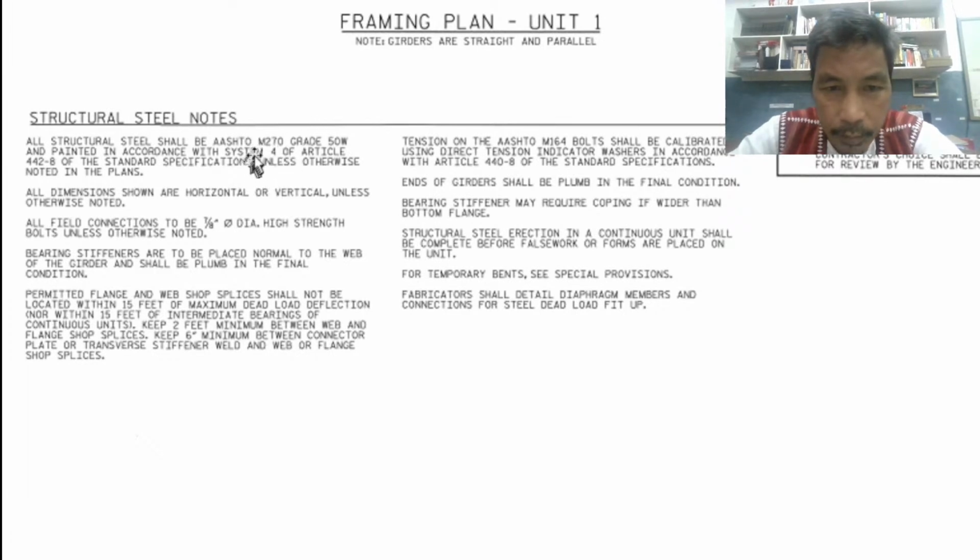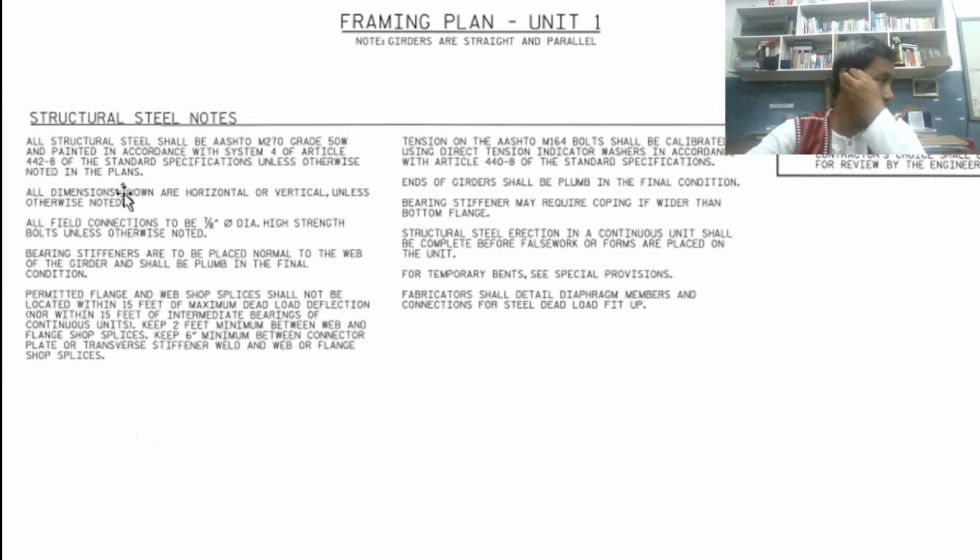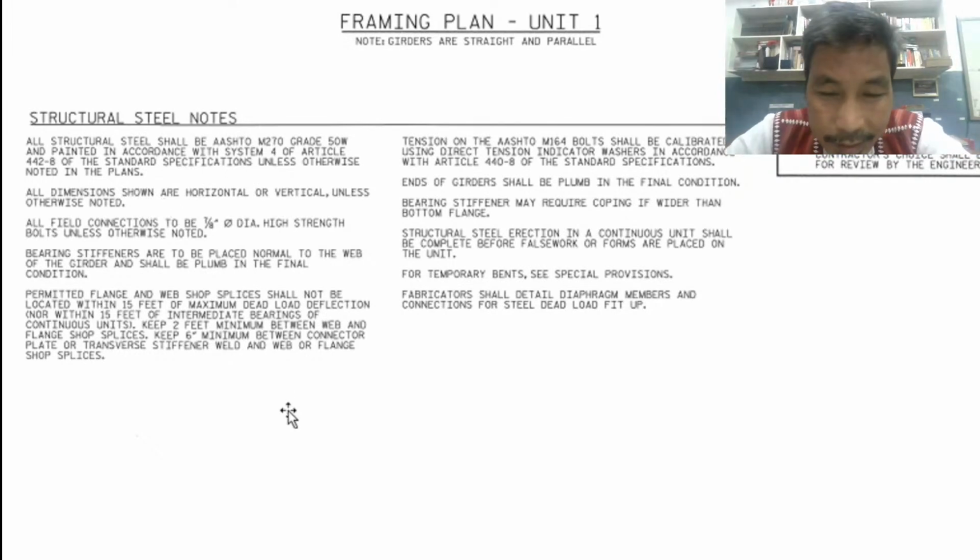So M270 grade 50W and painted in accordance with System 4 of Article 442 of the standard specifications unless otherwise noted in the plans. Take note.